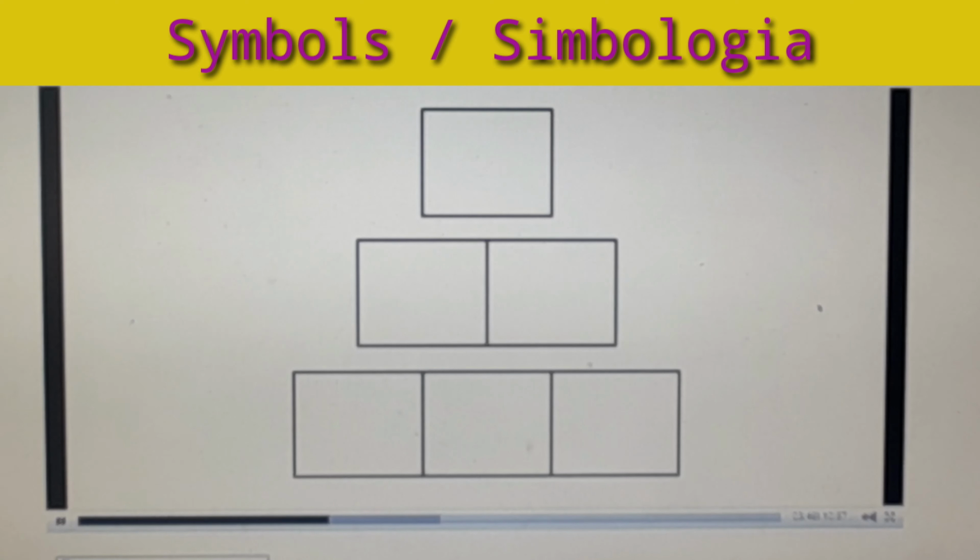Valve positions are represented by individual boxes. A single box represents a single acting valve. A double box indicates a two-position valve. Three boxes represent a three-position valve. Pressure-compensated proportional valves are represented by two lines that run parallel to the valve position boxes. Port connections of a valve are depicted by arrows inside the position boxes. Flow path arrows, or ways, are also shown inside the position boxes.